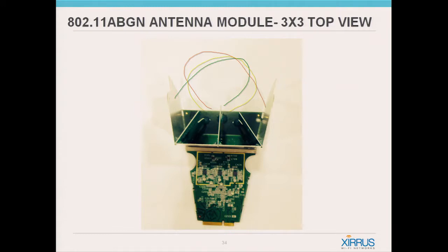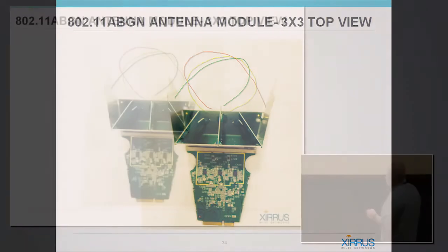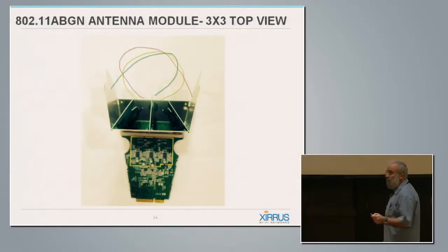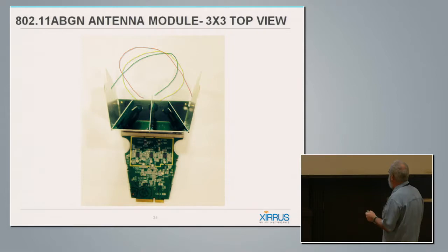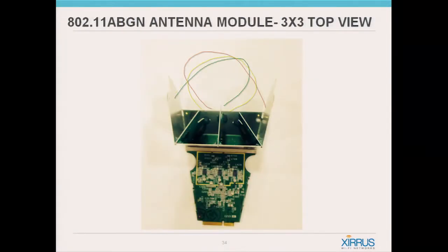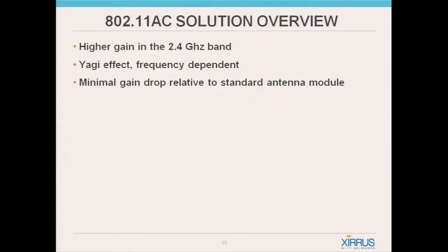It's very challenging to do overall because it's a narrow band phenomenon, but if you look on the other side, which I'm not showing, there are some other tricks that I'm doing in order to make it broadband or dual band, to work both at 2.4 and 5. And actually, that's one thing that I later improved when I went to the 11AC design.